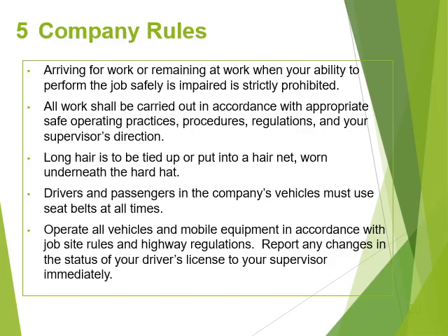Long hair is to be tied up or put in a hairnet worn underneath the hard hat. Drivers and passengers in the company's vehicle must use seat belts at all times. Operate all vehicles and mobile equipment in accordance with job site rules and highway regulations. Report any changes in the status of your vehicle's license to your supervisor immediately.